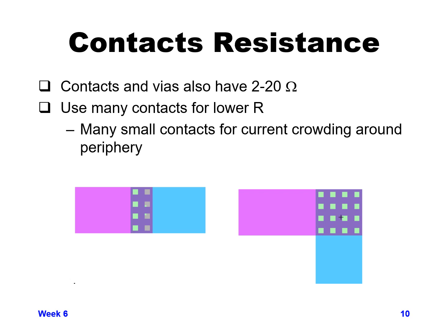If you really want to lower your resistance, instead of putting a single contact to your active or a single via between, let's say, a metal 4 wire and a metal 5 wire, you might want to make a bigger area and place an array of contacts. Like, for example, shown below, there are 2 different examples here: one where they have a 2x4 array of contacts, and the other where it's a 4x4 array.